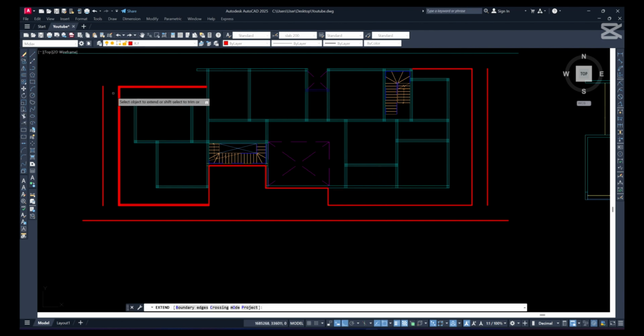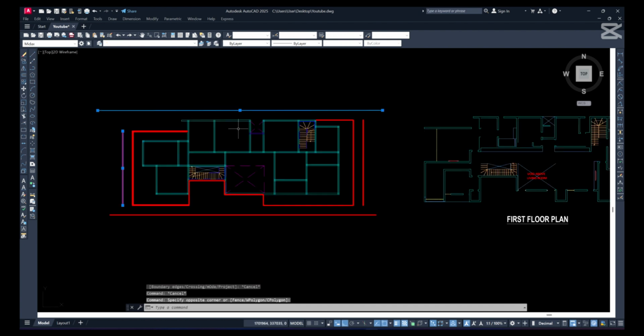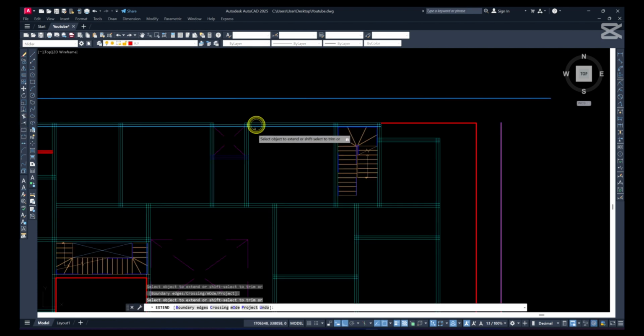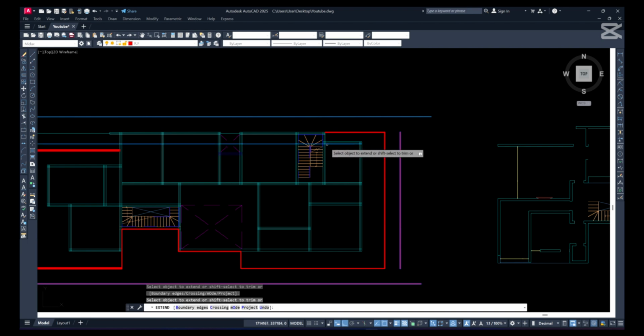So now you see why I was saying that for our beams, the lines should be one single line. If you have multiple broken lines, you can't offset it in one go, you have to start offsetting multiple lines. But if it's just one line, when you click on offset, it offsets the whole beam. I don't know if you get what I mean. Let me offset this now.